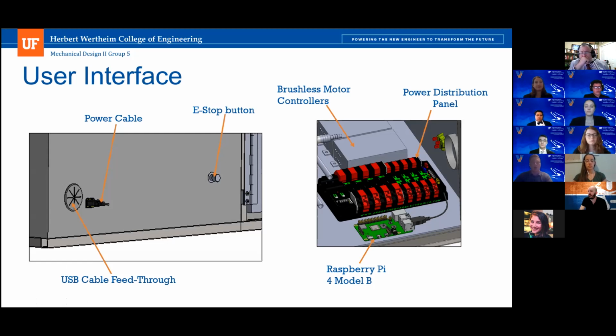In terms of e-stop, there's a digital e-stop button on the laptop program. And if for whatever reason that doesn't work, we have also placed a physical e-stop button, as you can see in the left-hand picture, that physically cuts off power to the microbioreactor. So whatever safety reason might happen, and the digital e-stop doesn't work because, say, it caught on fire and the Raspberry Pi was destroyed, you could physically hit that button and kill the whole system. Next slide.